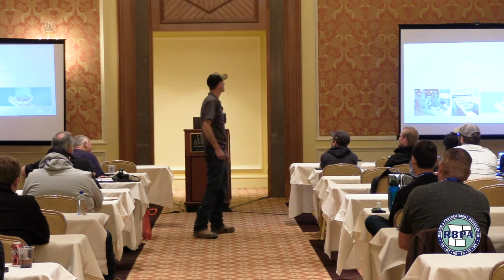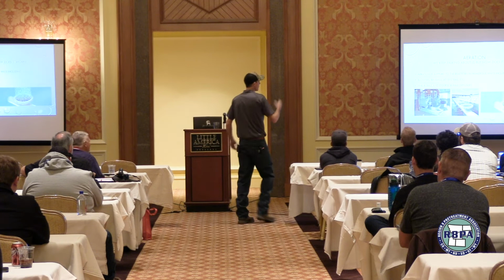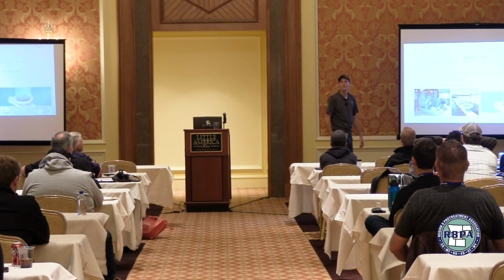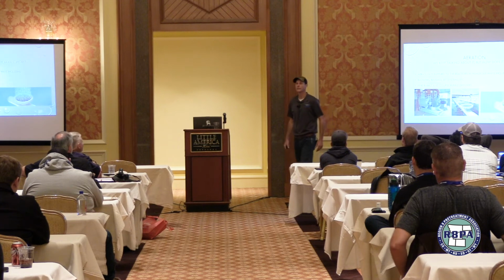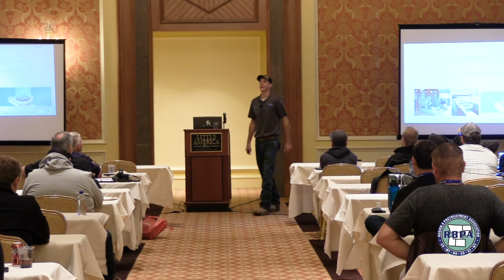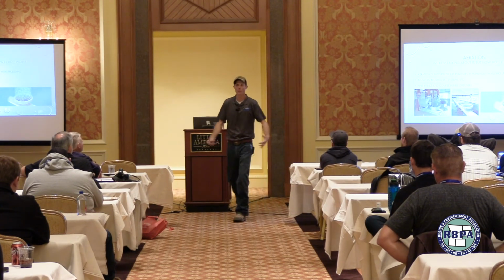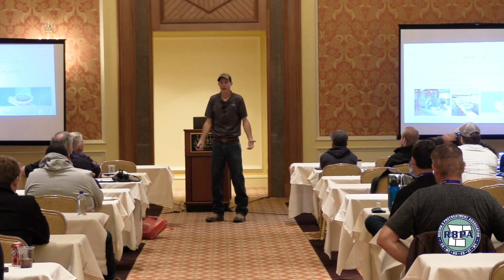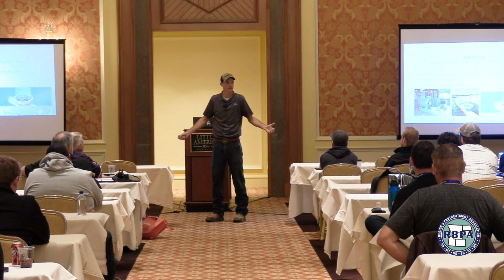Yeah, exactly. So in an aeration system that we're using for wastewater treatment, do we want a fine bubble or a coarse bubble? Why? Surface area. Does that make sense? You get one big bubble, you've got this much surface area. If you have a billion tiny little bubbles, you've got more surface area, right?